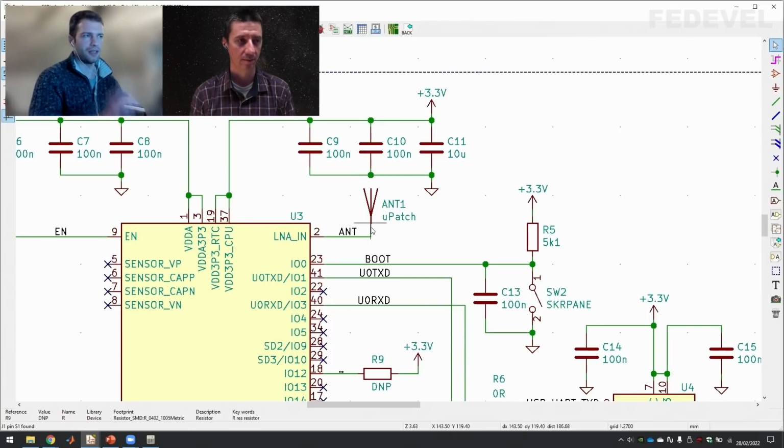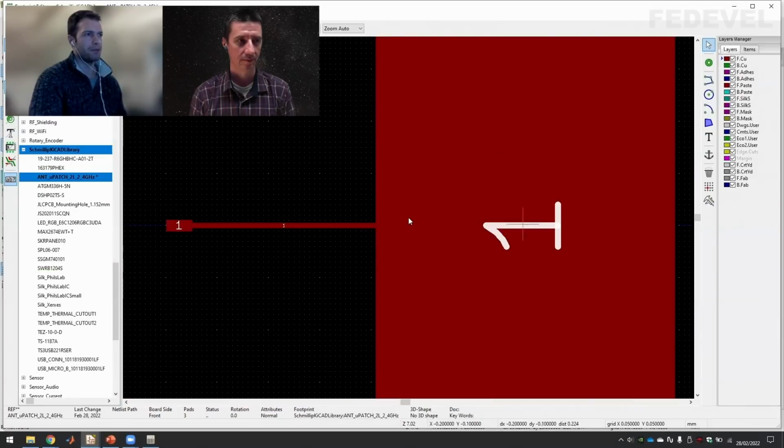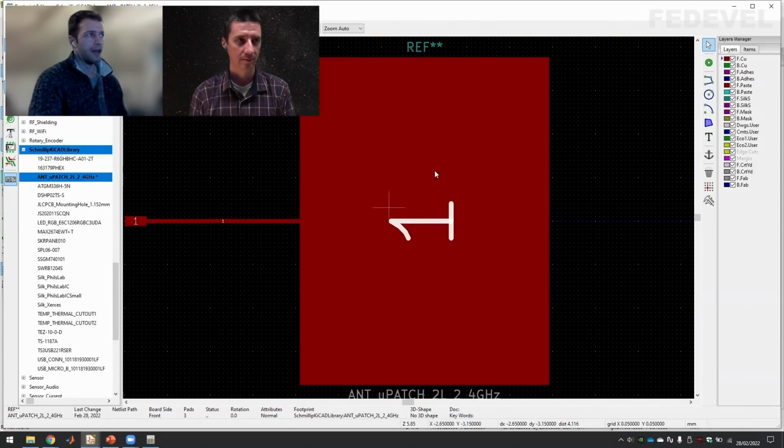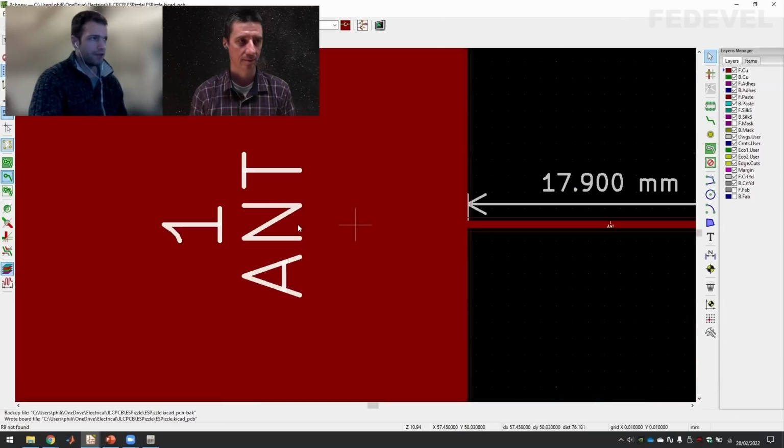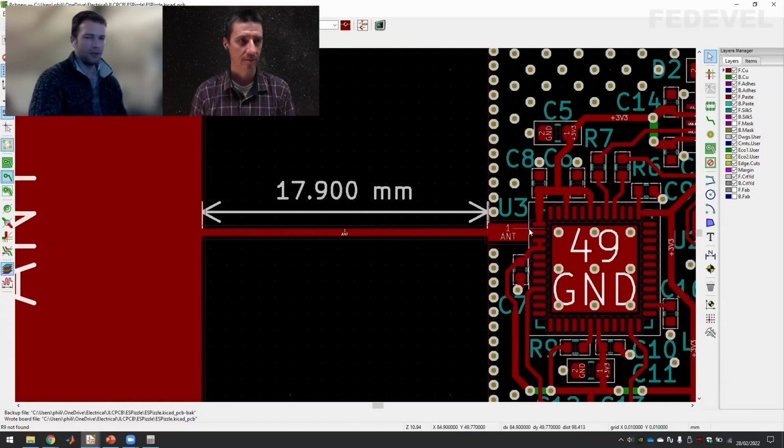And then I just say this is pin 1, and then this maps pretty nicely to my symbol. I believe in KiCad, actually, I've drawn a very thin trace through this footprint, because KiCad doesn't see them as connected, even if they're edge to edge. But this is of course invisible if you just draw a 0.1 millimeter trace through. The DRC doesn't throw any errors.